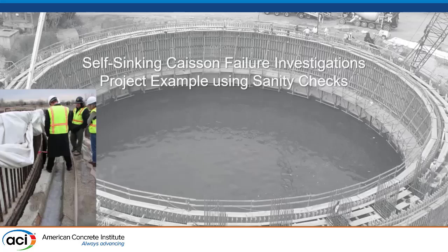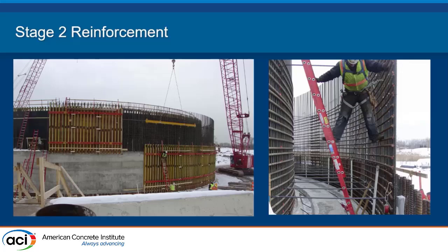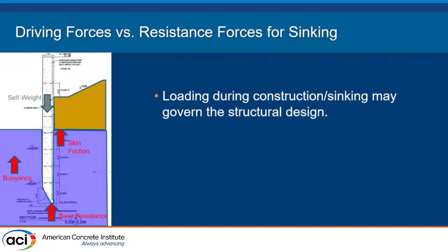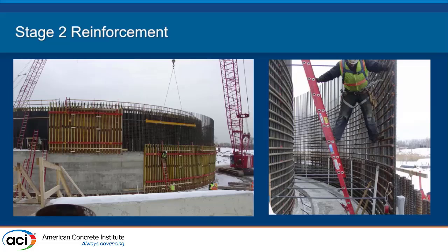It's 136-foot diameter. The walls are 7 foot thick. Here's some reinforcement cages. You can see they were like number 11s at 6 inches on center, front face, back face. And this is the stage where they built the first two stages, and they built it on timber cribbing. Once you get the first two stages, you pull the cribbing out, and this thing starts to sink under the ground as you're building the next stage, and you keep building and getting it to keep sinking.